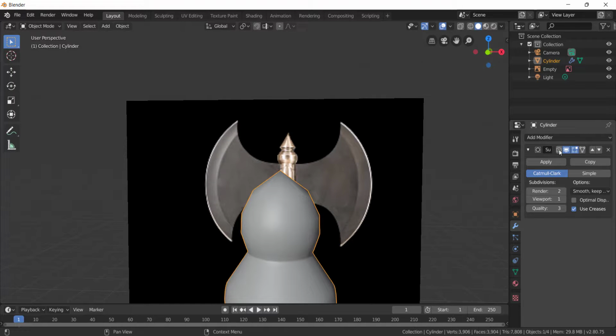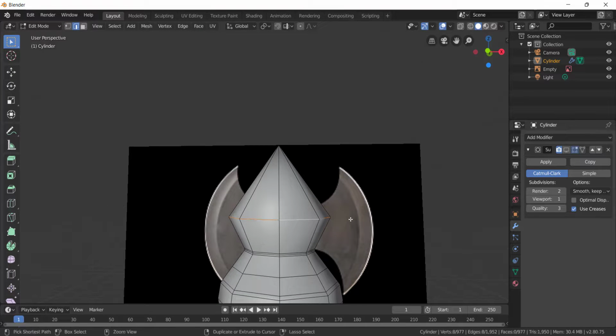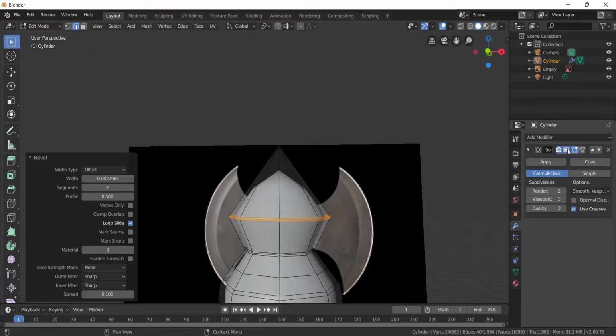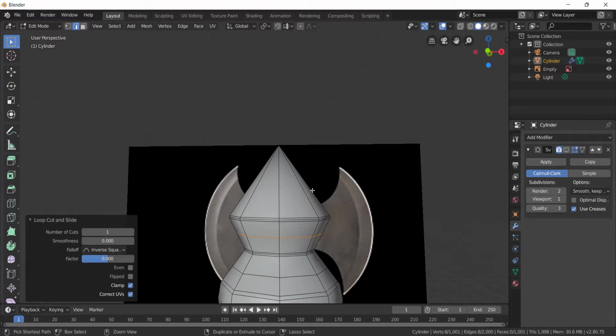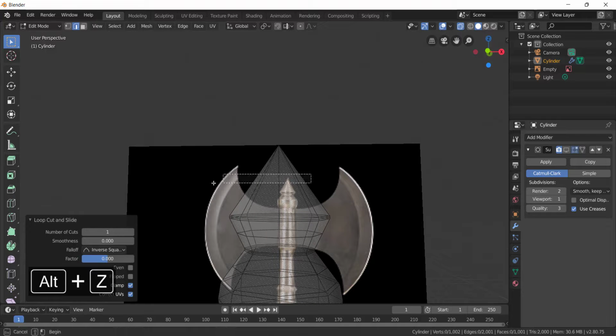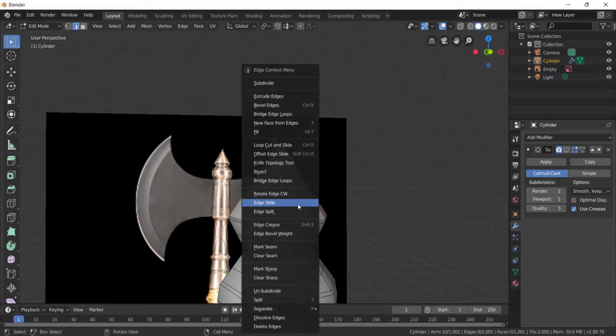See, becoming smooth. Don't want that. So to change that, you should select this one and Control B. Yes, it looks fine now, better, but you can add a little more here and select these edges. Okay, and you can connect it.